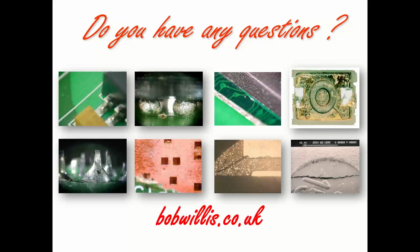If you're producing boards where each board is worth a couple of £100 or more, a really good polyimide construction, so it's 22 layers, it's a big board, of course you're going to bake it, because you want to minimize the possibility of damage. You've got to weigh out the cost return, the cost of baking, and also the liability of a board and product failing. So you've got to balance all that up.